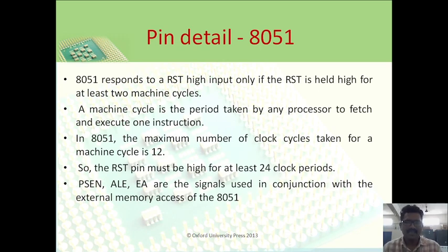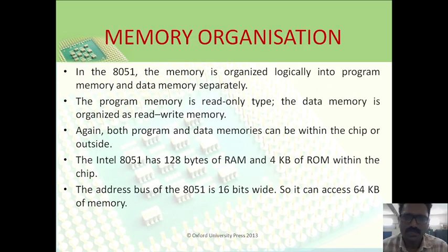PSEN and ALE are the signals used in conjunction with external memory access of the 8051 microcontroller. Coming to the memory organization of the 8051 microcontroller, the memory is organized logically into program memory and data memory separately. The program memory is read-only type. The data memory is organized as read-write memory.